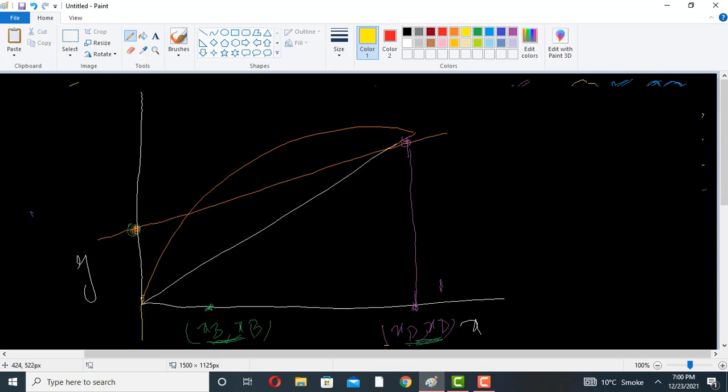Also determine the y-intercept, or first find this xW, then find the y-intercept of the stripping line, or find the slope of the stripping line. Suppose you determine the y-intercept, so connect these two. Connect the stripping line with the rectifying line, and then start the plate numbering. You can start from this side or from this side. So start from this point to the equilibrium curve,